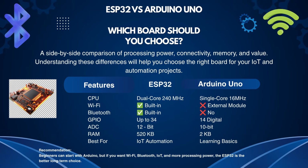Now, let's compare the ESP32 with one of the most popular development boards for beginners, the Arduino Uno. Understanding the differences between these two platforms will help you choose the right board for your projects. Let's start with the processor. The ESP32 features a powerful dual-core processor running at up to 240 MHz, while the Arduino Uno uses a single-core 16 MHz microcontroller. This gives the ESP32 significantly more processing power for complex applications.